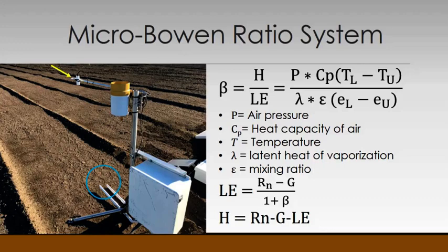It is, in fact, a net radiometer, but a neighbor sitting right next to it is an infrared thermometer, also measuring surface temperature. The net radiometer is more horizontal to the surface, kind of flat. And our infrared thermometer is right here, and that measures surface temperature at our soil surface. I forgot to mention that in our measurements. So that allows us to get surface temperature measurements.